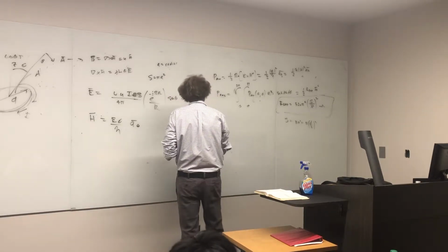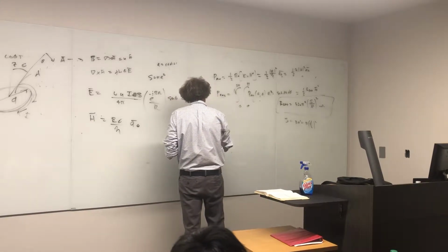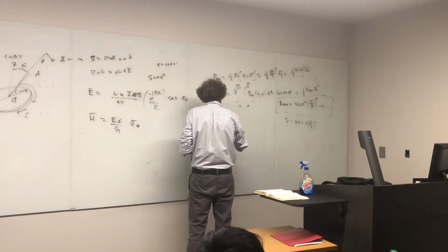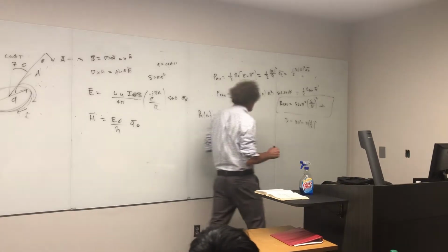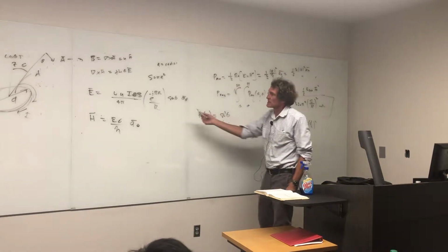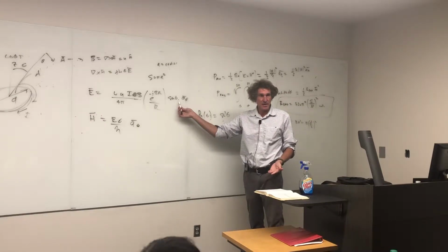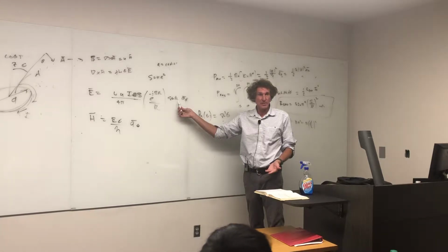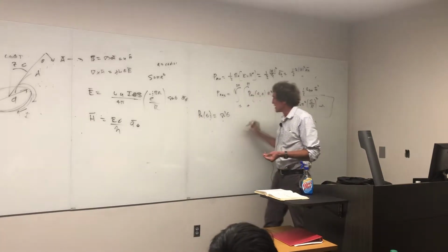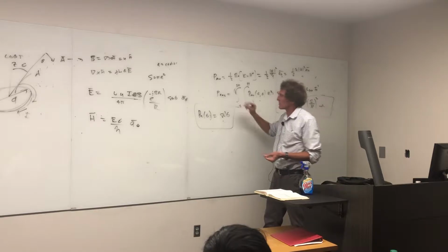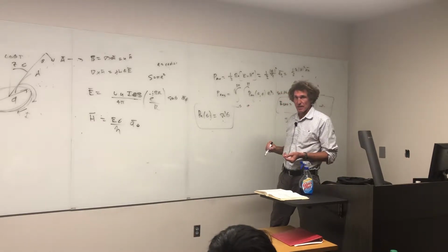The normalized power is going to just be sine squared of theta. If you look here, the E field here is a function of theta, right? Sine of theta. The power would be the square of that. That would be sine squared theta. When we get the normalized power for the short dipole, for the small loop antenna, it's that. Follow me?